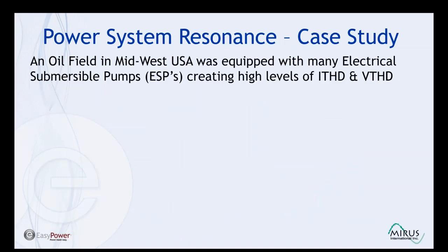So let's take a look at an application where the addition of power factor correction capacitors made distortion levels much worse. In this case, we have an oil field in Midwest USA that was equipped with electrical submersible pumps. So these pumps push water or some fluid into the ground to force up the oil when the natural pressure isn't enough to bring the oil to the surface. There are a lot of these devices used in these fields. They run on variable speed drives and they draw a lot of harmonics.